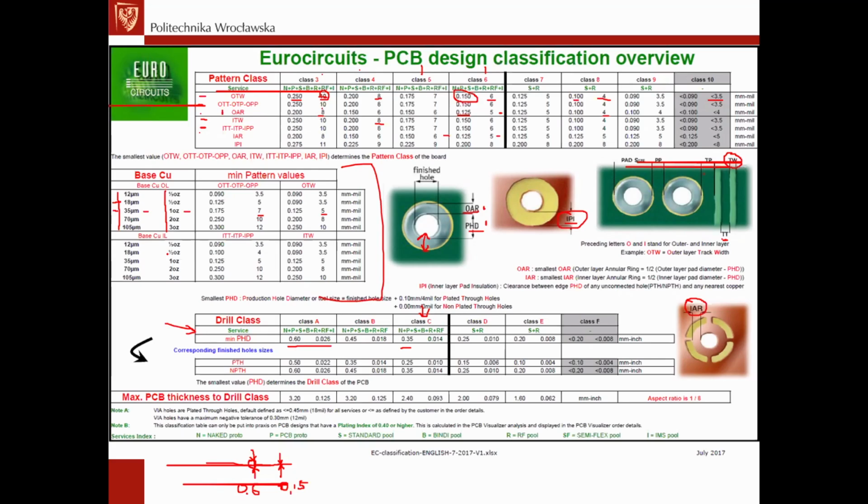They're half the height, so they must be twice the width. So we have better technology like 5 mils, actually very nice, but the tracks we must make wider, of course those that are to withstand high currents.